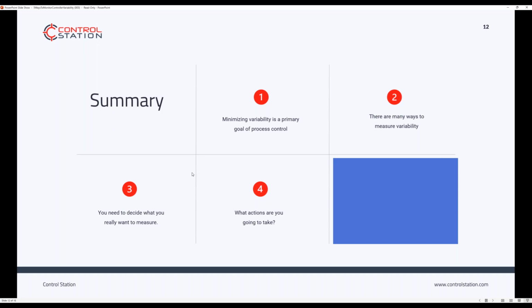And as you move through this scenario, you're going to find yourself with alerts and actions. Unless there's ownership and accountability and a flow chart of what you do once this information comes in, it won't work. What do you do when a valve needs to be fixed? What do you do when a loop needs to be tuned? What happens when a loop is oscillating, when a valve detects friction, when a loop has high normalized variance? What do you do, right? What is the process? So there need to be documented SOPs.